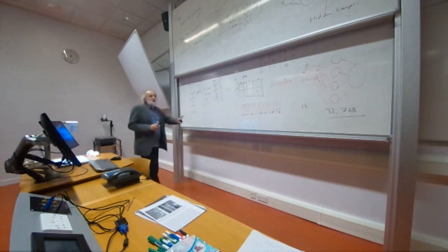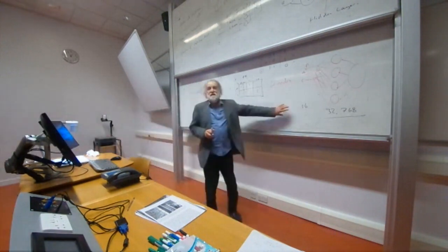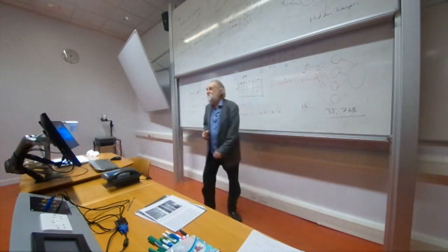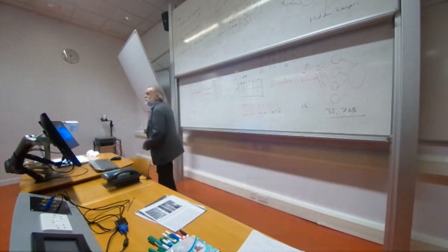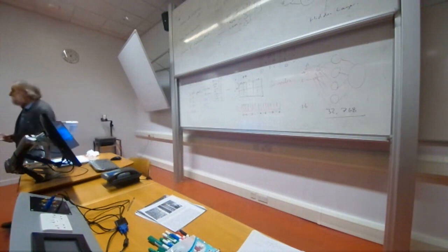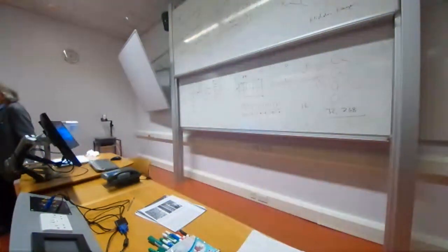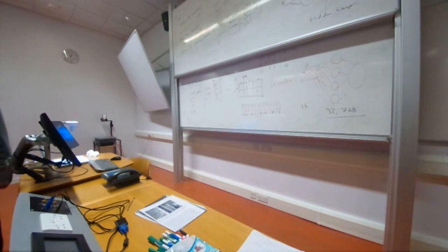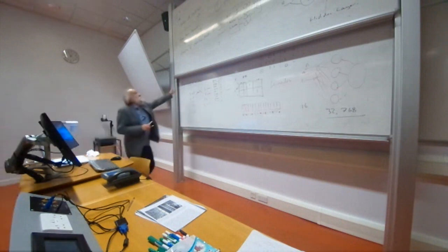What did we do in logic design to solve this 16-bit problem? We didn't build a canonical form that had 32,000 AND gates on the top there, did we? Don't cares? No, don't cares. Parity is fully specified. We used a cellular structure. And the cellular structure doesn't take the full input.